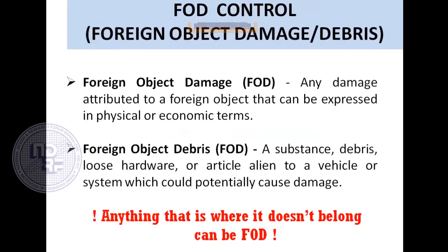Now, another unique quality practice in the aircraft industry is foreign object damage. As I told, the aircraft is a machine which flies, takes off, and needs to land safely. One of the most important things to be ensured before it takes off is that there is no item installed or present in the aircraft which does not belong there. There have been so many instances where aircraft have been lost because of very small objects in the aircraft which were originally not supposed to have been there.